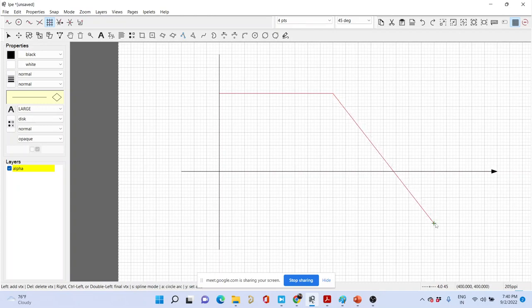This is the magnitude plot of the plant that you have. Now, for increasing the gain at DC, at very low frequencies, in order to make this gain very high, what you have done is you have introduced an integrator. So what would happen now is the plant becomes somewhat like this.